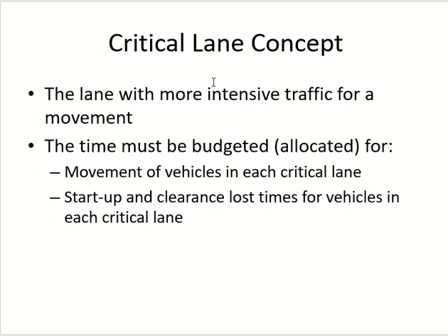Okay, now I gave you the example of 200 and 1000, right? So 1000 obviously takes more time. Okay, but what if I have left turning 1000 and straight 1000? Which lane is critical then? I know the volume is same, but which lane is critical? Left, right? Because it takes more time. Even if the volume is same, I know the left turning will take more time. And in some cases, even if the volume is less, because of the turning, it may need more time. So 900 left turning may need more time than 1000 straight. Okay, so for the critical lane, you have to look at which lane needs more time.